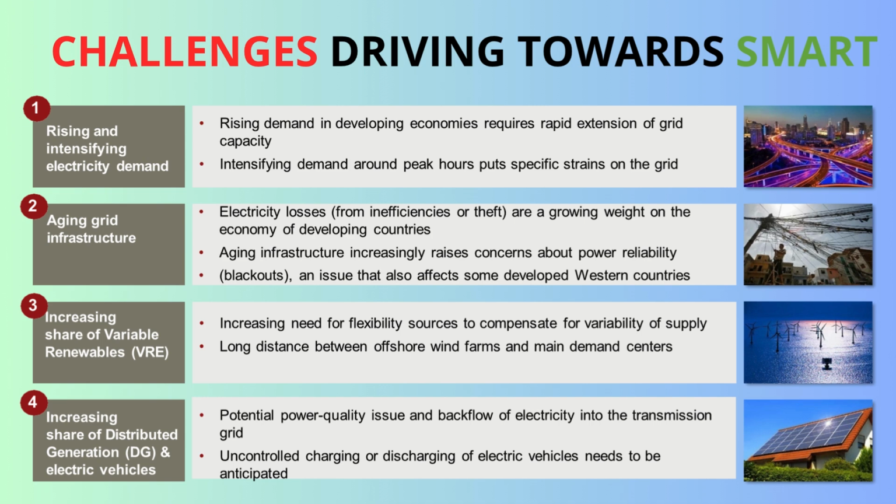And then there's potential power quality issues and backflow. We touched on this. We did. Distributed generation, like rooftop solar, can cause problems locally, like voltage getting too high on a neighborhood circuit. And if enough power flows backwards onto the higher voltage system, it can cause instability because the system wasn't designed for that reverse flow. It messes with protection schemes.